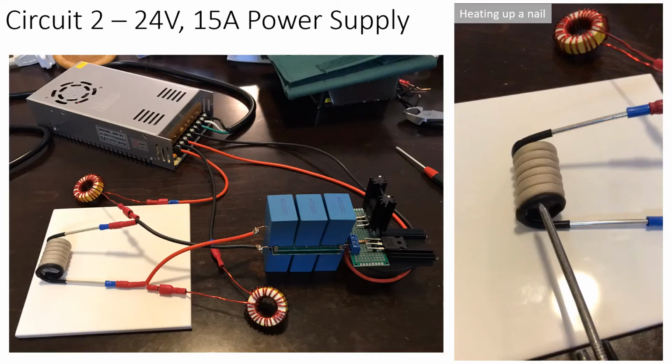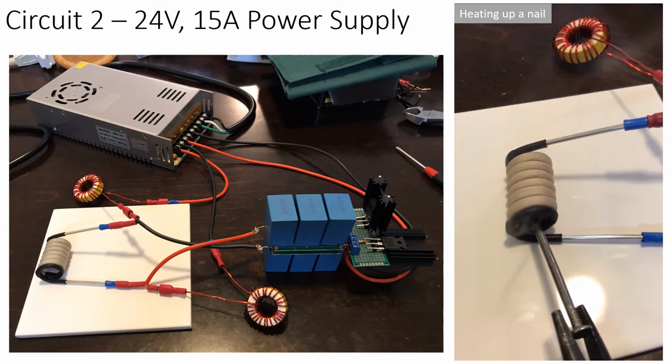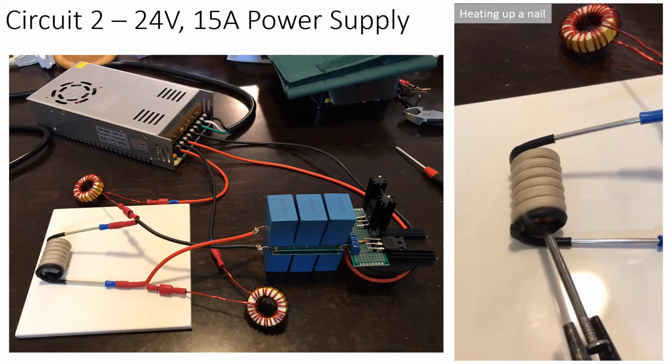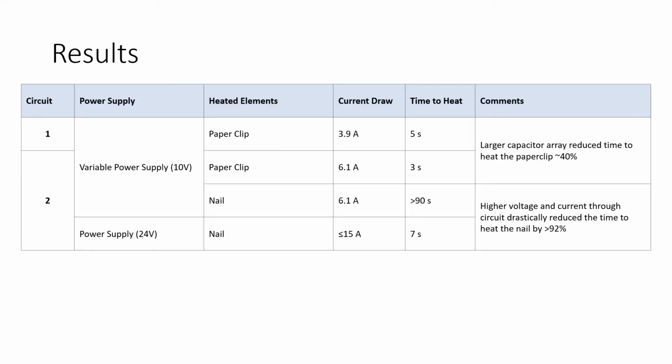Lastly, I connected circuit 2 to a 24 volt 15 amp power supply. I inserted an identical nail to the last experiment, and it now heated to a red-hot glow in only 7 seconds, which was a greater than 91% improvement. This improvement in performance was a result of the increased current flow through the coil, which caused a stronger magnetic field. The results from all of the experiments are detailed in this table.